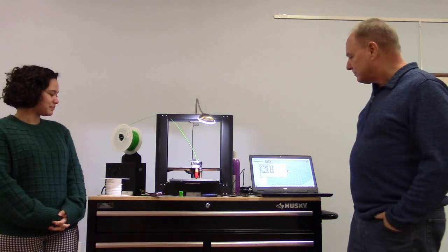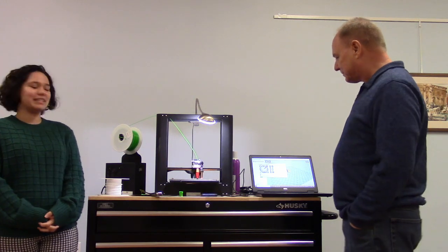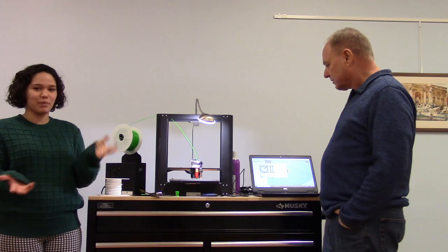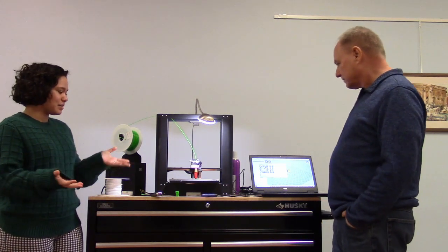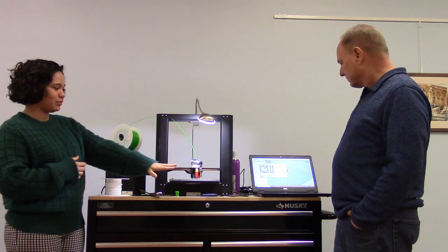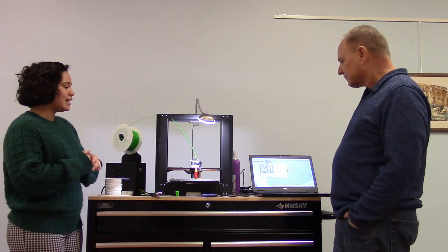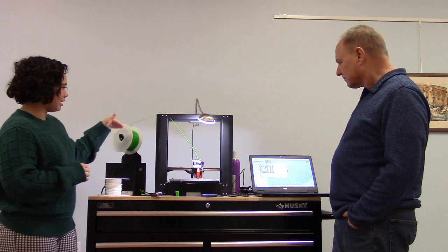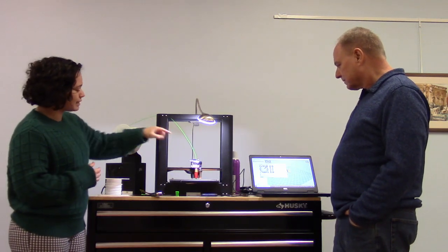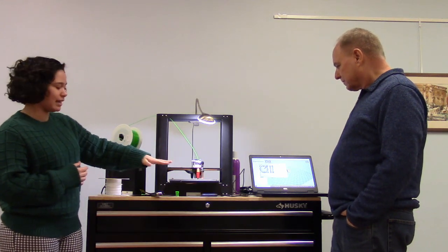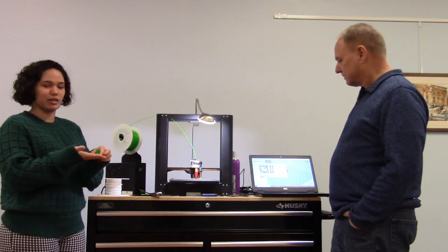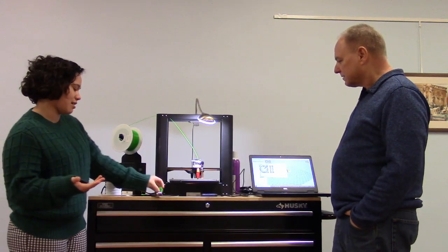Rachel, can you tell us what you got going on over here? Absolutely. So today we are actually printing off one of our little creepers that we have from Minecraft. And basically the simplest part to do this, you would choose your design and upload it into whatever software you have available. It's going to go into this machine here, which pulls from a PLA, which is a plastic filament. It heats up through this nozzle over here, and then layer by layer it builds up into your design, which today, as I said, we're using our creepers, but can be whatever you decide.